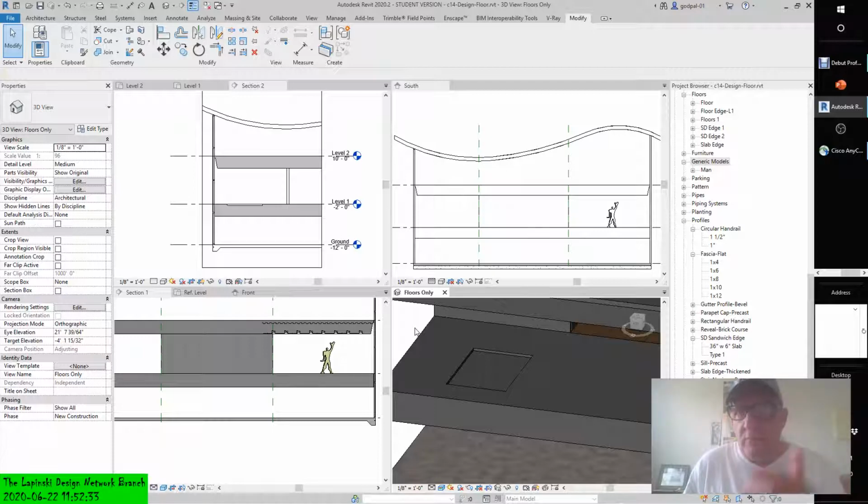Now, technically, if you brought it 3 inches down and created the extrusion 12 inches up, you would still get that effect. You would have 3 inches cut from the top of the deck, from the cut plane 3 inches below the level, and then an 8-inch void space above that, which would cut anything else that was in its place. But this particular floor slab doesn't have anything above 3 inches, right? All right, if that makes sense to you.